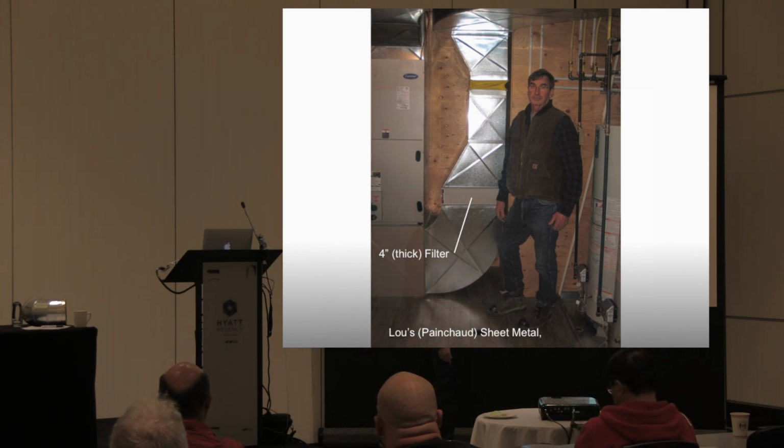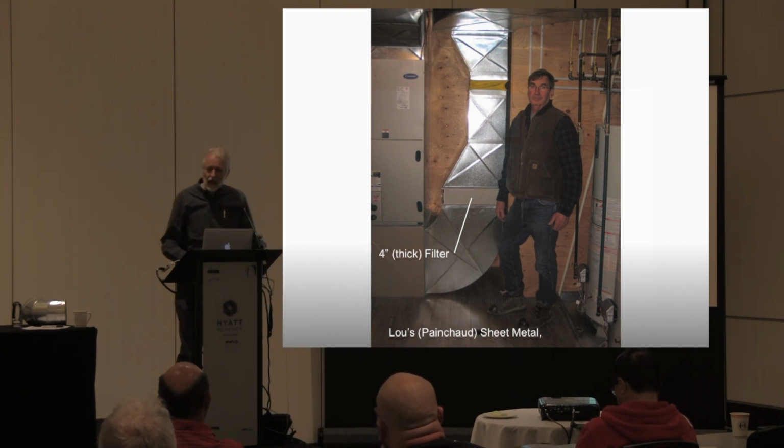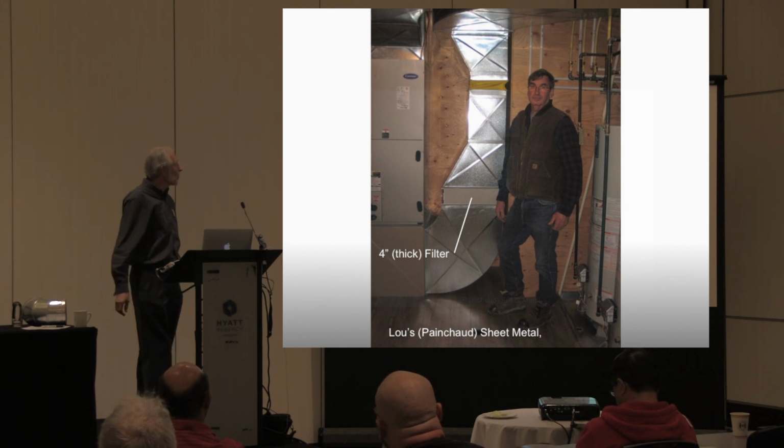He's got a tapered fitting at the top because air doesn't want to enter a sharp throat square fitting. Flex connector, so he's isolating his structure from his appliance. He's sound lined out as well. I mean, everything you could ask for has been done right, and I bet he didn't spend more than $500